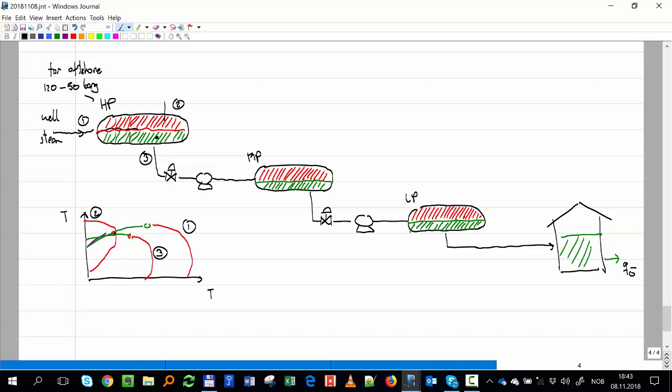So any further reduction in pressure I make on number 3, what will happen? To take it to the pump, it still has to go all the way to the pump, so it has some pressure drop in that pipe. If I put it high, the pressure drop will have to climb up and gas will be liberated, right? I will start to come inside this region. If gas is liberated, that's not good for the pump. So usually I have to place that pump lower, just to get some positive NPSH.